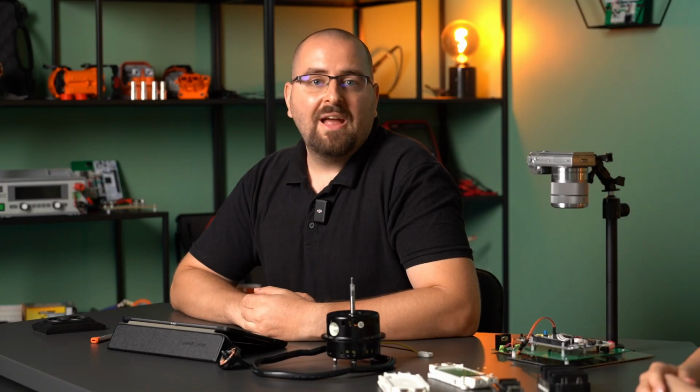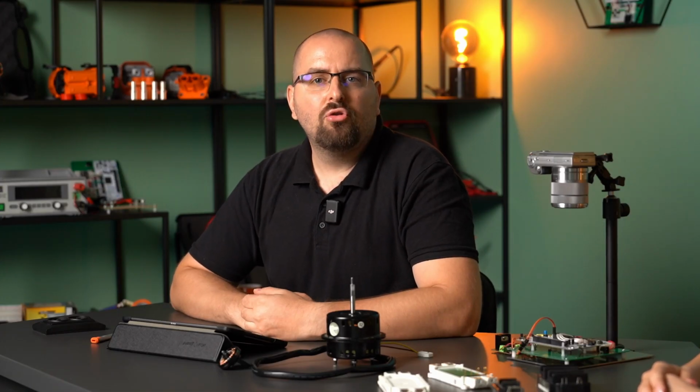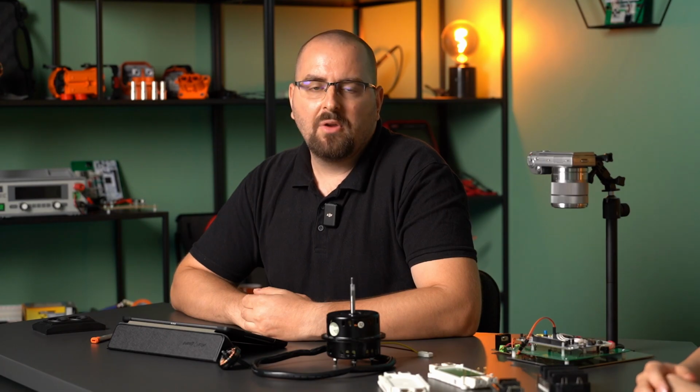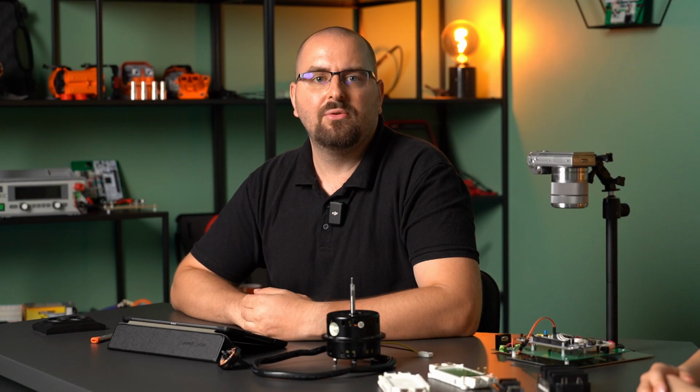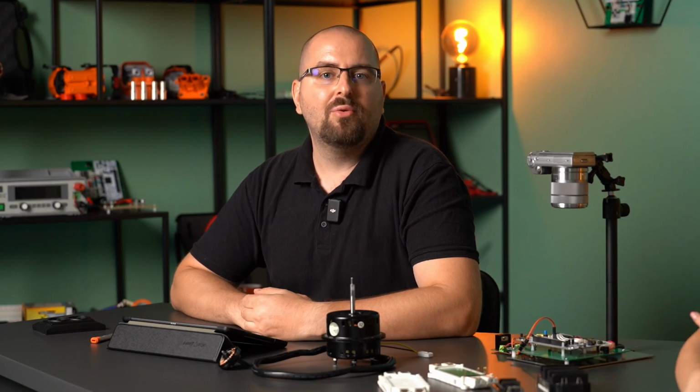It is important to note that the single-phase AC motors used in power tools and kitchen appliances are actually DC motors with series excitation. These are called universal motors because they can operate on DC or AC power. The motors described so far were all equipped with a mechanical commutator. With the development of semiconductors, it became possible to extend the range of electrically commutated motor types.